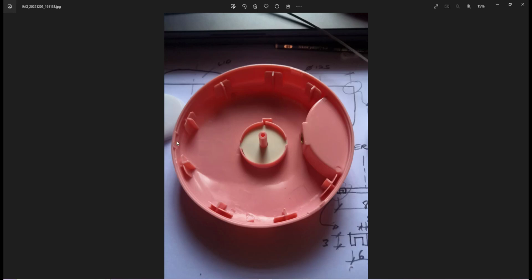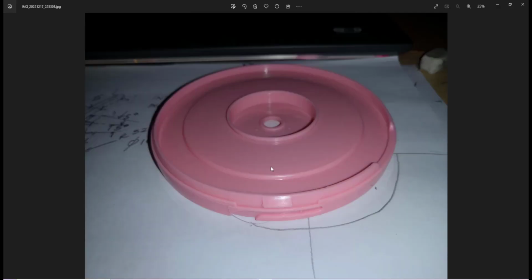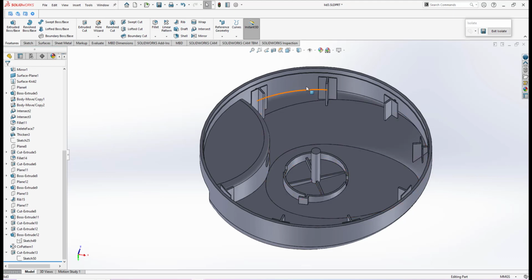Okay, for this lid modeling, I will not do the groove, because groove means we have a cutting here. I will just do the base for the cutting, because the cutting will be done later after I have finished the modeling of this middle plate. When I've done the modeling of this middle plate, I have a hook, a snap feature here. Then this middle plate will be inserted into this modeling, and it will make a cutout. This one will be shown in the next video.